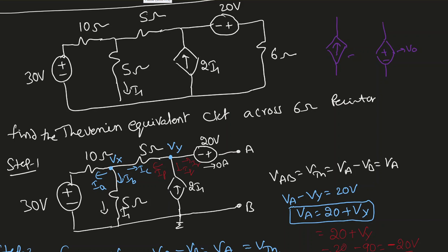In this video, we're going to solve a couple of examples based on the Thevenin theorem. Here, we're going to have a dependent source. Whenever we have a dependent source in a circuit, while finding Rthevenin, we need to do some extra steps. We're going to talk about it. Now, how do you know it's a dependent source?